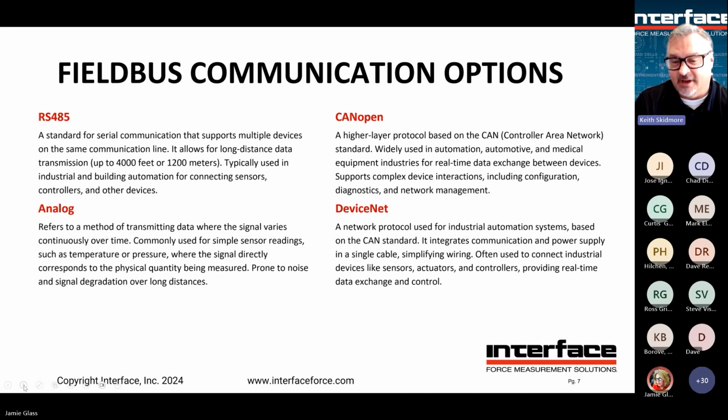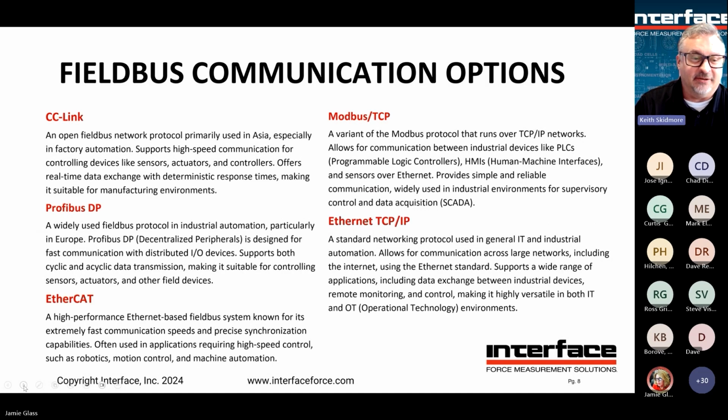We got CANopen, DeviceNet. There's no one protocol that really is correct or right. And the answer typically is, what is the existing network? So you don't say, oh, I'm going to use DeviceNet. Usually you're using some controller that uses DeviceNet, and now that dictates that your other devices want to be DeviceNet. Next slide, we have some other protocols.